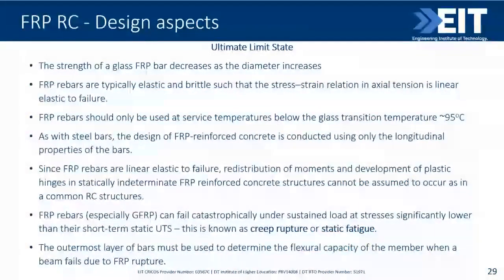Design. So we're looking at the ultimate limit state. I believe many of you are familiar with the idea of limit state design. So we've got ultimate limit state, sometimes called strength limit state, but it includes more than strength, includes stability, includes the fatigue as well, and serviceability limit state. So we will address here too.